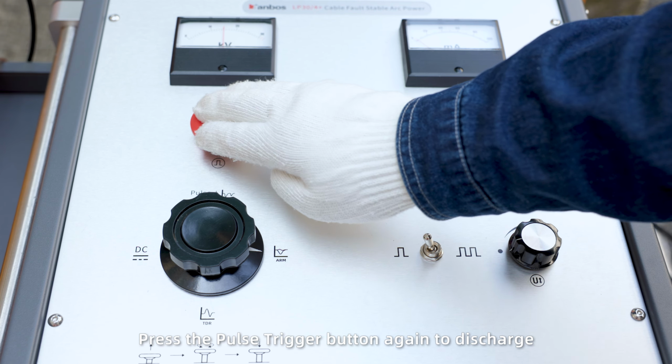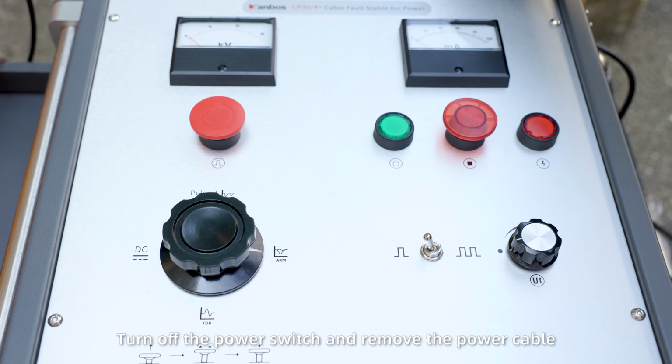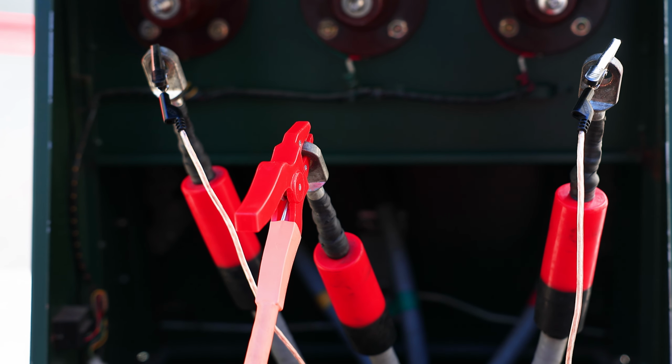Press the pulse trigger button again to discharge. Turn off the power switch and remove the power cable. If testing is finished, use the discharge rod to discharge the cable before disconnecting all wiring.